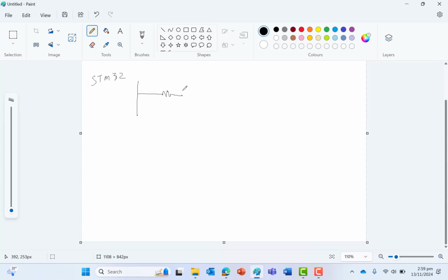The LED can be connected this way. This is of course the anode and this is the cathode. This resistor is to limit the current. It can be a small number, 470 ohm, 330 ohm, 150 ohm. All these are small numbers. This pin, let's say I'm using PA0, must be made an output pin. When you send a high, or logic 1, or 3.3 volt, the current can go this way from A to C, and the LED will turn on.